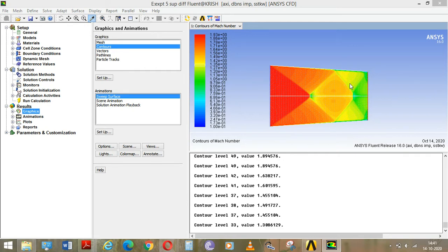With the shock wave, 1.3, 1.3, and ultimately it has to come and land at Mach number 1. So if you do your iterations up to convergence, if you do another 500 iterations, the accuracy will further increase. Now it is showing 1.16. Further, if you iterate, it will reduce to 1. Okay. So this is one way of seeing using this data pointer.